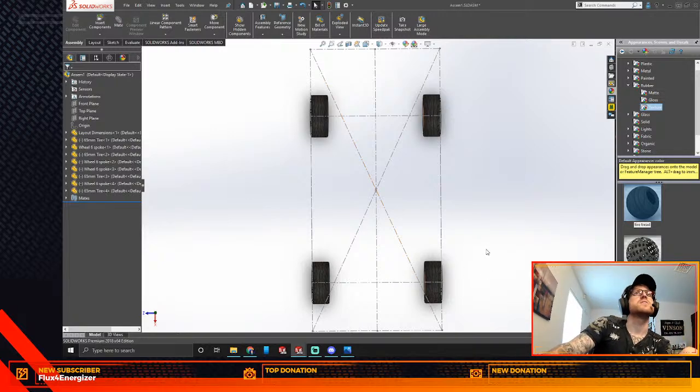As far as the air goes, it needs to get skinnier, thinner, right around here. So what we can do is have the chassis plate a little bit higher and then have a 3D printed section go down a little bit lower to get that squeeze for that low pressure zone. And then we'll have the chassis plate cut out behind here for attaching the large diffuser.